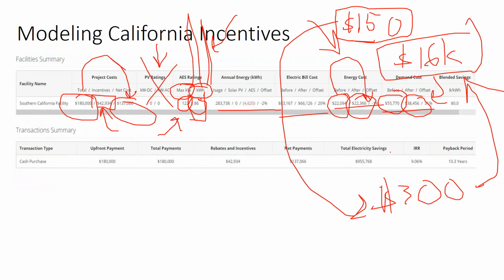It's just that the demand savings are so great. And for that matter, in off-grid, you're oversizing your solar capacity to the point where for most of the time in the spring and the fall and most summer days and sunny winter days, your efficiency doesn't matter either because you're overproducing. You've designed your array to be much larger than normal. So it's kind of ironic that in off-grid and in commercial demand management, the efficiency of the system is not really a critical factor.